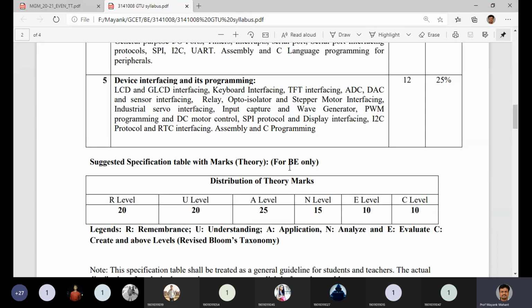Now for output, we generally use a relay or an opto isolator. Generally we use relays for turning things on and off. You would have seen applications where, if temperature increases to 35 degrees, a fan must turn on. So how can you operate a relay with your microcontroller? There is a chip which is required to operate a relay, that we will be looking at. An opto isolator is generally used to separate the control circuit from the power circuit.